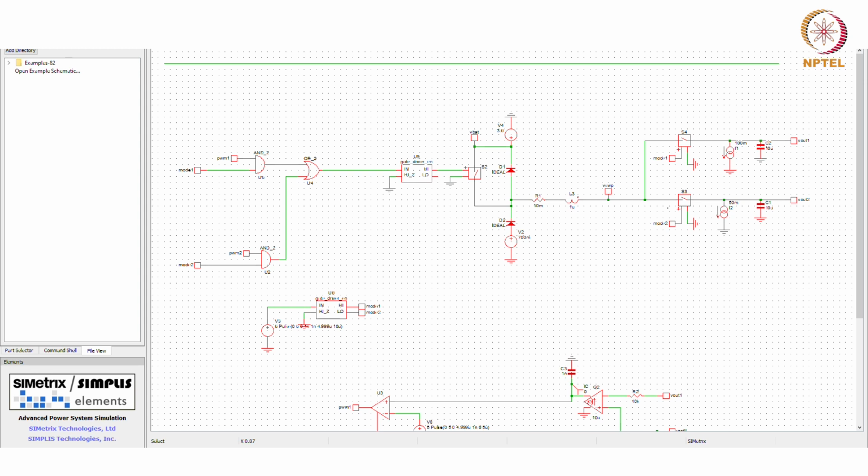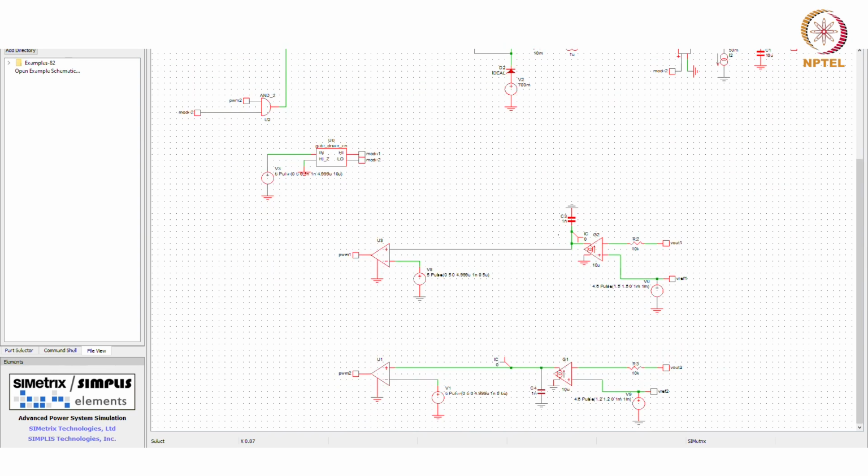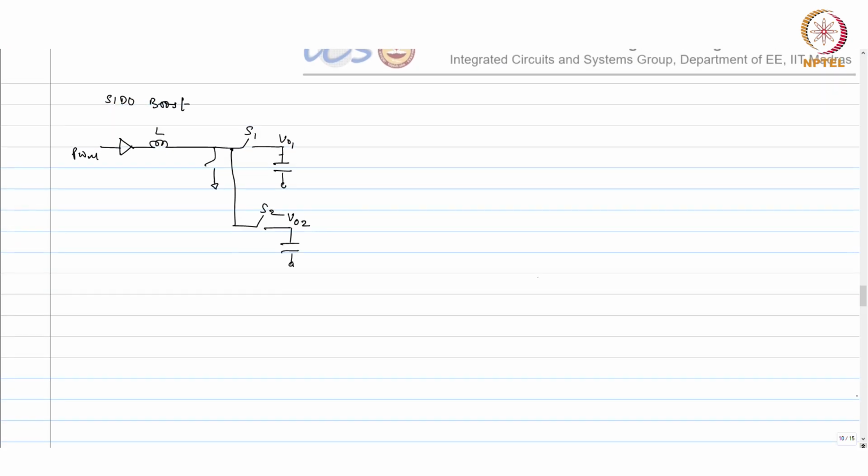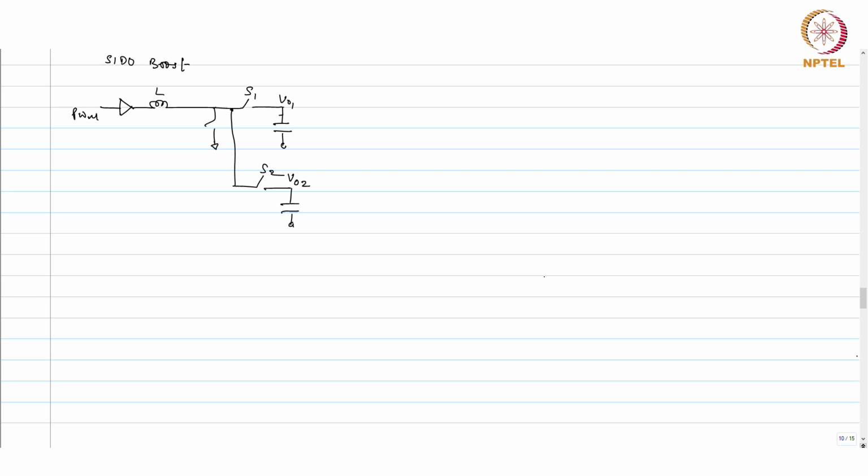So that's why you need another third control or third time duration, which will avoid the cross regulation, and you short the inductor. In that case, you are basically intentionally making the inductor current zero during that time. If it balances out, then you are fine. But that won't be in all the cases. There might be cases where it may not balance out. So the control is not simple there. Cross regulation is the main problem with that, and that's why it's not very successful in the CCM.